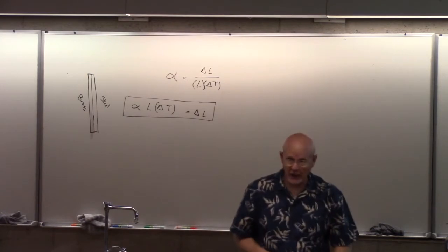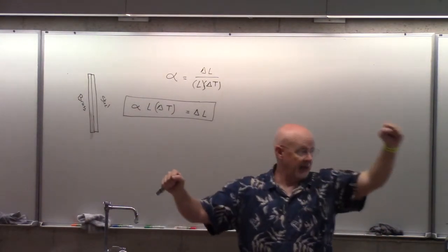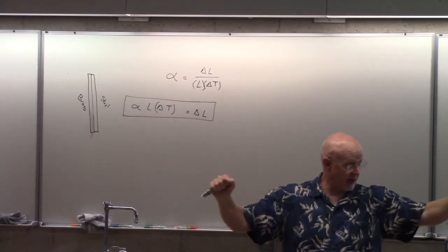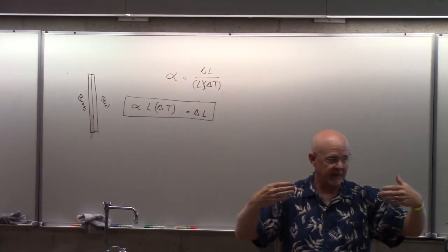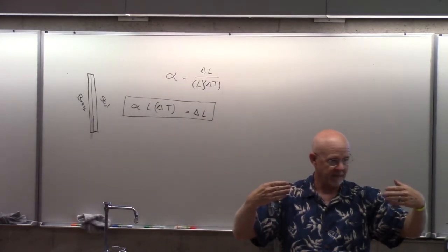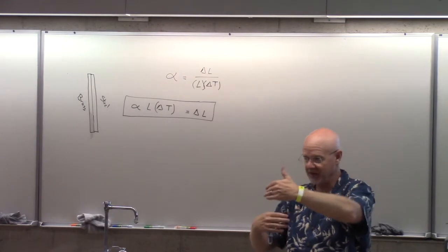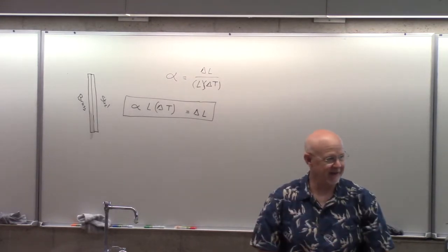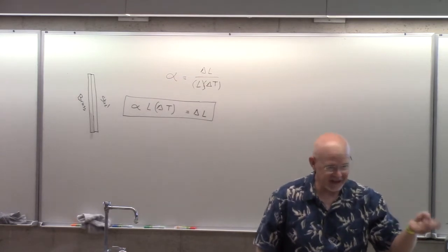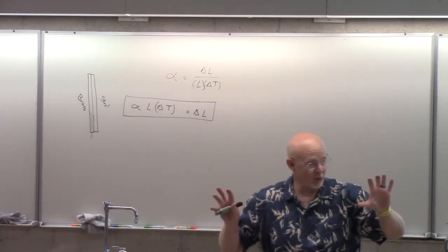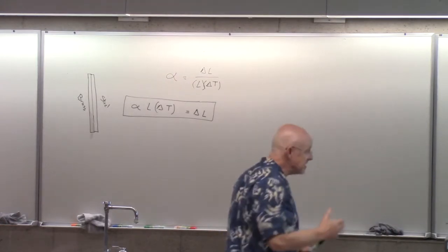And if you just took a metal beam on one side of the bay and connected it to the other side of the bay, and then it grows, what happens to that beam? Well, it'll now be twisted, something like this. You don't want to lock both ends of the beam. You want to give it room to grow. And this is a small bridge.